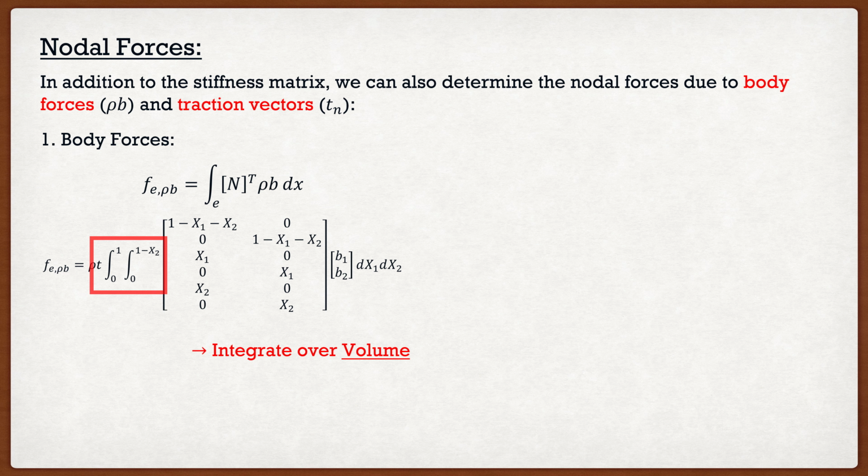Now, one of the things I get from a lot of students is they say, all right, I know how to calculate these body forces, but what exactly am I doing with this integral? Well, it's actually very simple. If I had this element here, we know that this element is subjected to gravity, which acts over the volume of this element, which is why we integrated over the volume of the element. Now, the problem is when I'm actually solving my system, remember, it's a function of the stiffness matrix as well as the nodal forces and nodal displacements.